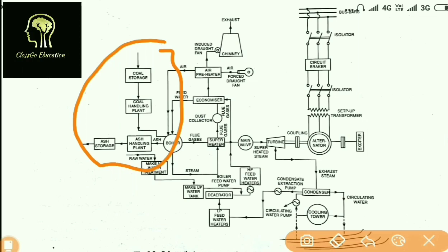big coal blocks are basically crushed into various bunkers and then pulverized into smaller granular parts. Now what will actually happen is that in the boiler section we have a furnace as well, where the combustion takes place. Very small-sized coal is burnt in the furnace, and with the help of combustion in the water tube boilers the steam is produced.